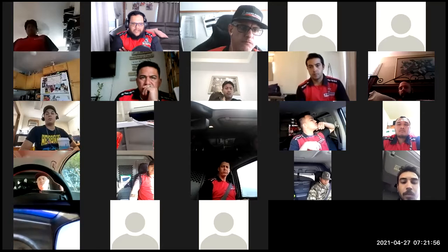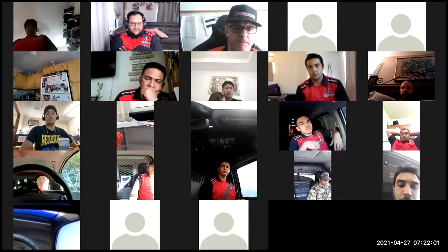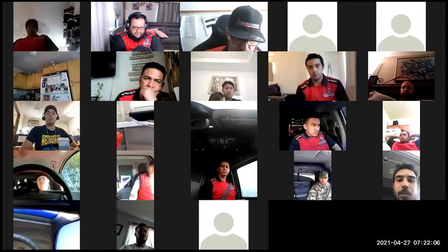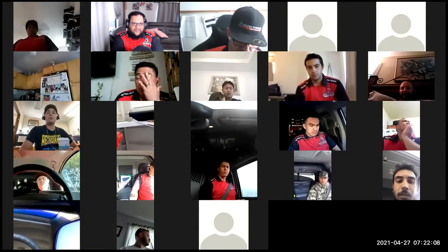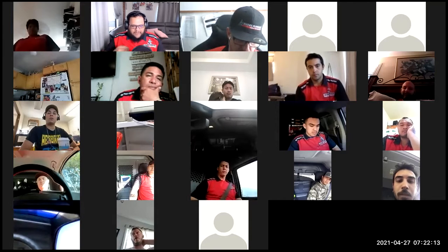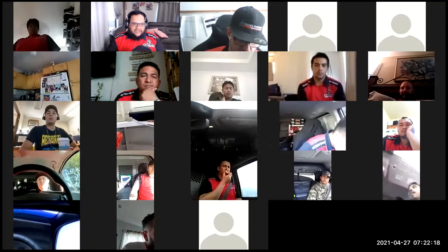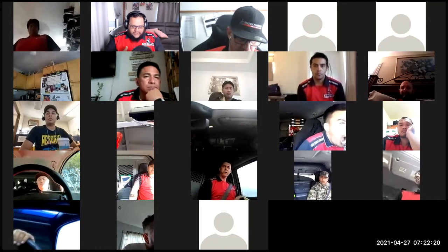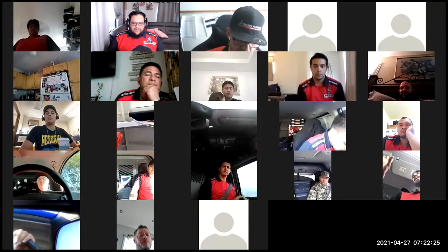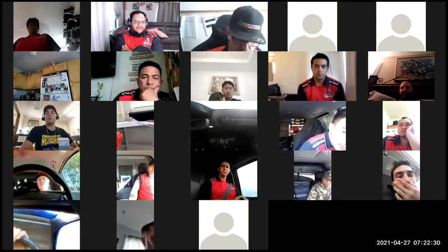What we did is we shot everything outside, dry. We then wet it out on the tables, and then we pulled the pre-liner over the liner. We used the tape and everything. We pulled it through instead of trying to invert it because of the angle we had to get down the sample box we were working out of, which was kind of tough, but we were able to pull it through. We blew it up, and that was the whole procedure.